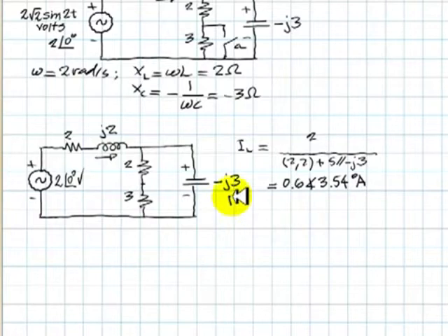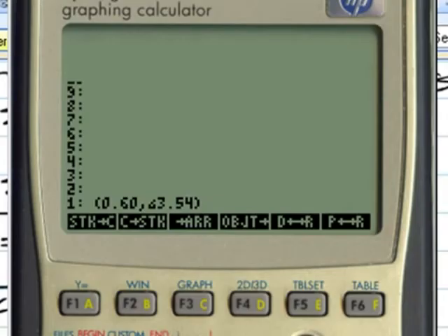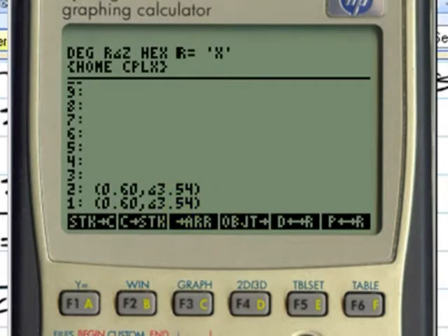The voltage in the capacitor is 2 volts minus the drop in that impedance, which is the value of that current IL that we just computed, multiplied by the impedance 2 + j2 of this branch. And we do that in the calculator. Let me duplicate that.